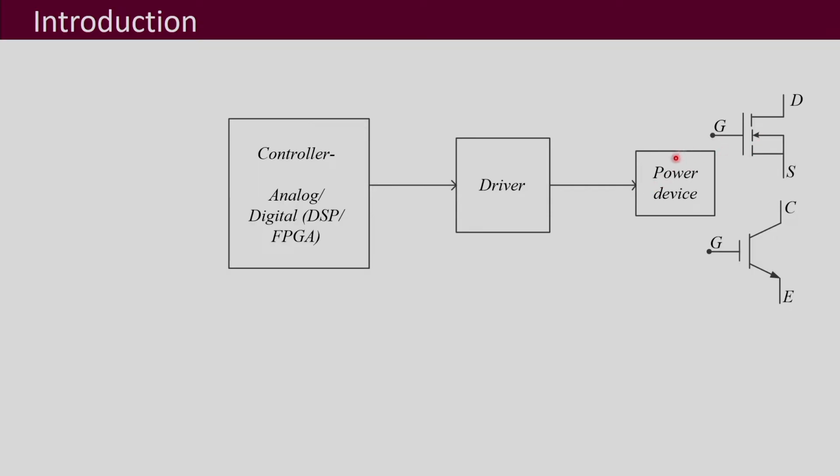Any power semiconductor device, basically your MOSFETs and IGBTs that we use very frequently, is connected with a driver, and that driver gets the signals from your controller.